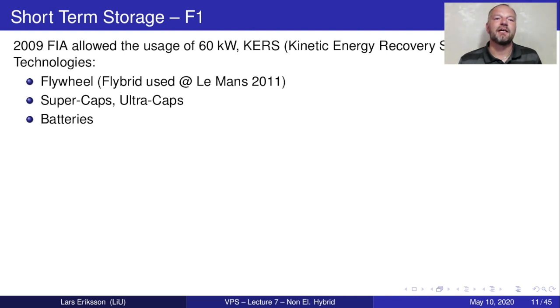In 2009, FIA allowed the usage of 60 kilowatt kinetic energy recovery systems in Formula 1, and a technology that was talked about then was the flywheel, and there's a company that has developed a solution called Flybrid. It didn't make it to Formula 1, but it was used in Le Mans 2011. Some use supercapacitors, and nowadays most are using batteries as energy storages.